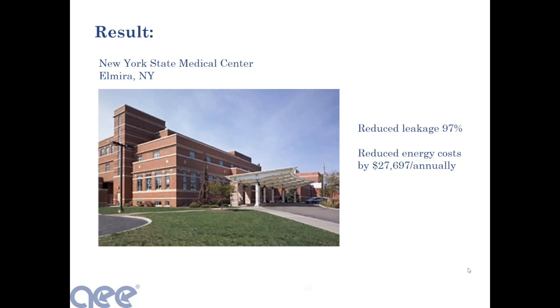So that's a great question. We're talking about VAV boxes because in a VAV box you've got a coil and a measuring device, typically a flow ring, right? So the way we would do this is the contractor would block off that VAV box so the sealing material would go up to but not through the VAV box. Downstream of it, they can either bypass that and go downstream, or in some cases, if there's not a whole lot of ductwork, they might just manually seal the ductwork downstream from that. But that is an important consideration. Good question. Yes, sir.